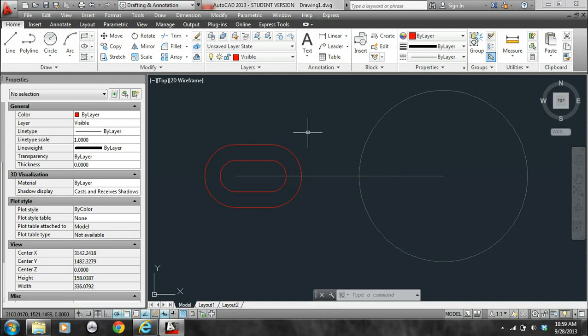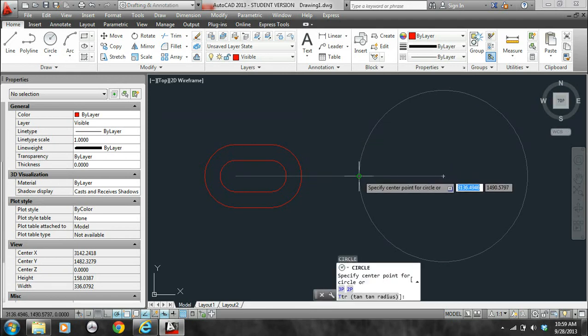This is telling whoever makes the part that the hole can have a tolerance anywhere between 28.52 and 28.57. In other words, it can be any size in between 28.52 and 28.57. So we're going to just draw it at the lower limit, at the quadrant of the circle or the intersection of the line and the circle, either one.